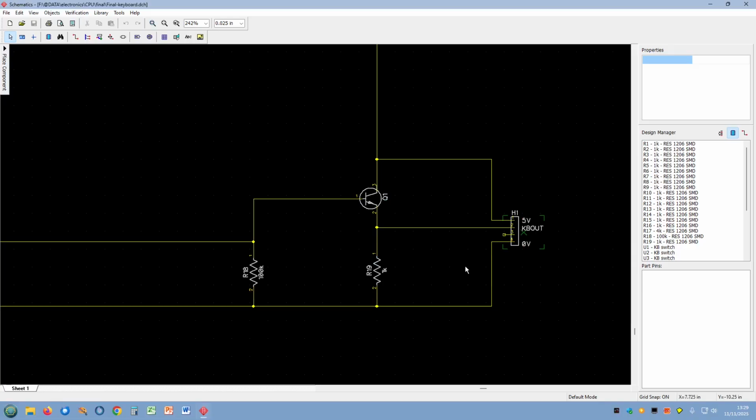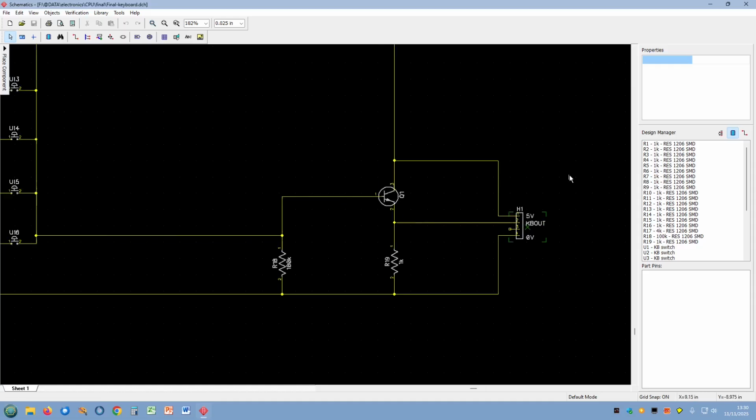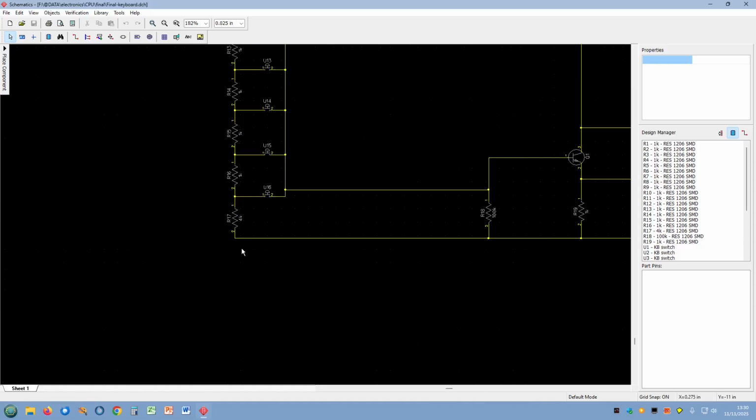Now this is a little bit supply sensitive. I could have built it a bit better, but it works well enough. If you know your supply coming in, which it says 5 volts, but on mine it's generally about 4.5, then your keyboard voltage is that. If this supply varies, the voltage coming out your keyboard will vary slightly, because this is a fixed 0.65 of volts across there, but the voltage that's coming out of these points here will vary depending on your supply voltage.